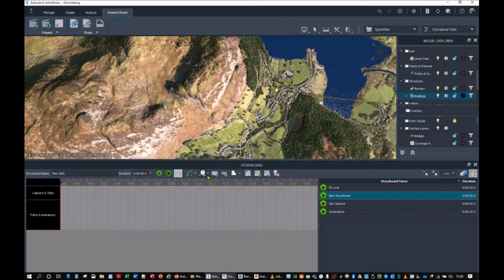This one here is all your different animations. So craning, looking around, orbiting, panning and zooming, walking, still motions, track animations, zoom animations, that sort of stuff. This one here is creating your camera path animations, or you can import it. Importing it's a bit annoying because it basically needs a load of points, and it creates a camera snap of each point. I would have preferred a line, you know, like in AutoCAD you can do it where it's a line and a camera follows a line. It's not like that. Or you can create it from a component road.